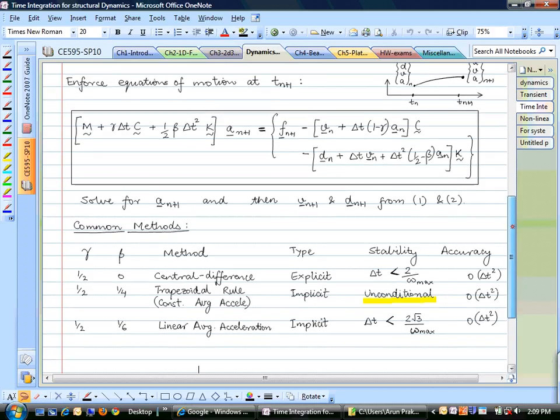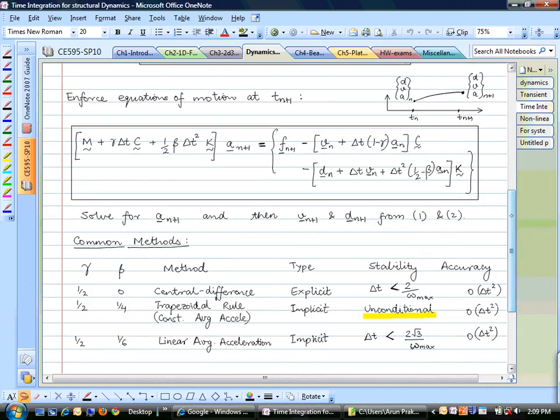So just like here, if I have this structure and I drop a ball on it, and I'm going to try to find out how this oscillates, I cannot use some big time step. I need to take very small time steps to figure out how this thing oscillates. And that time step is given by this limit, where this omega is the eigenvalue of the entire mesh. So, what you can keep in mind is that there is this limit for Abaqus explicit or general explicit